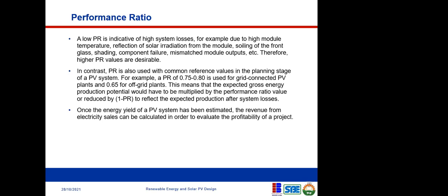Yes, you'll be on the safe side, but I don't want to say worst case scenario, because you could use 0.75, and when you do the actual measurement of your performance ratio, you could get 60, you could get 50. But just to be on the safe side, like you said, you have to come down from the nameplate capacity.